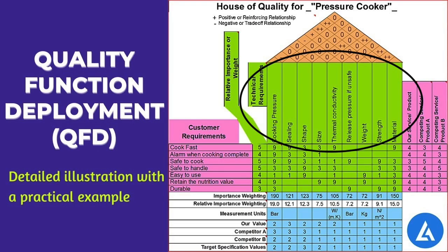Now, to fulfill these customer needs, you need to establish a set of engineering specifications or technical requirements. These must be quantitative, testable, and solution-neutral goals your product must achieve. It is vital that these specs are reflective of the needs, or your product will fail.